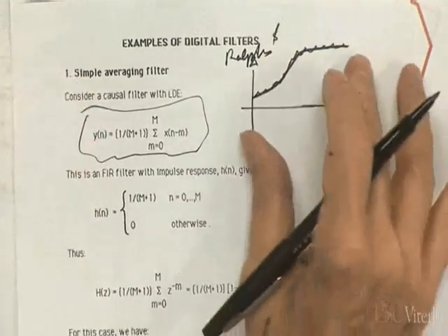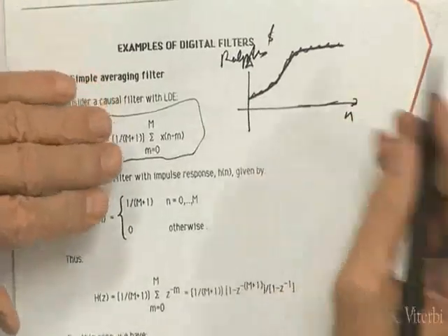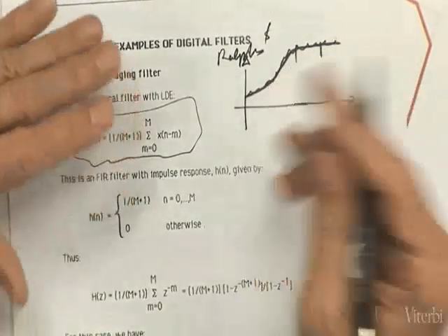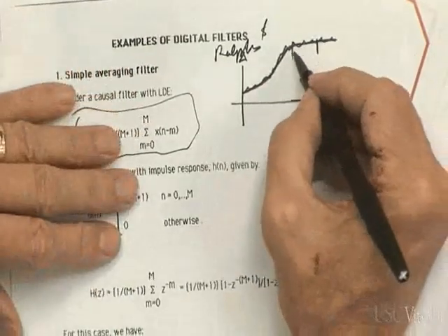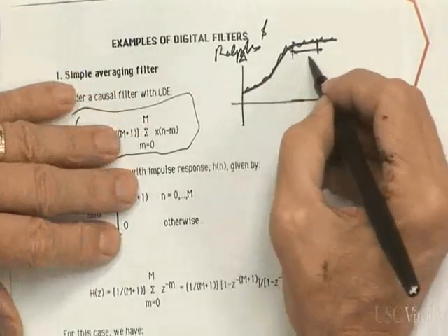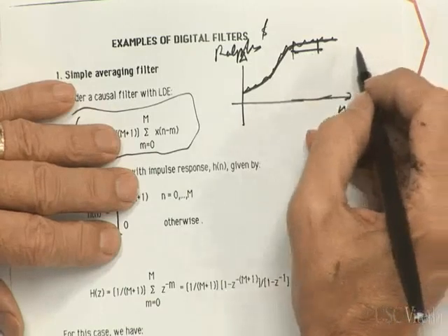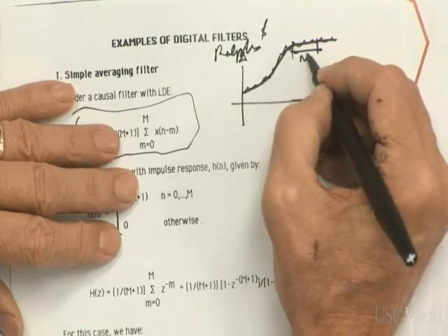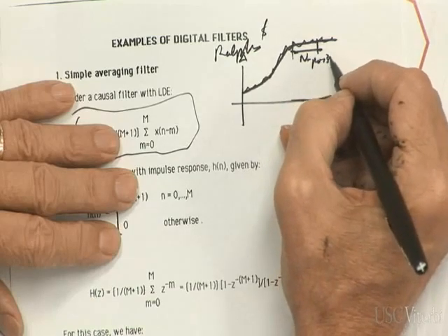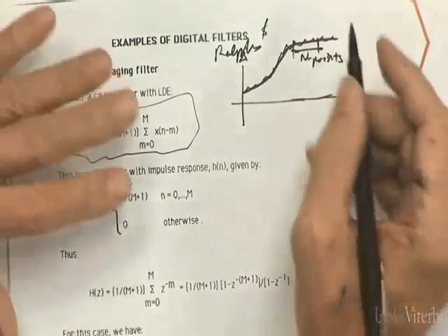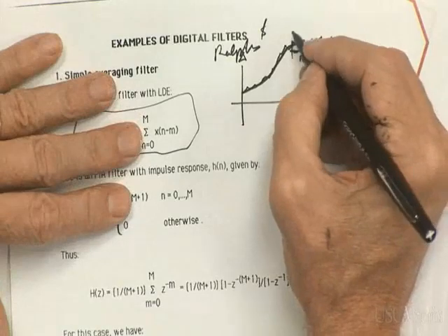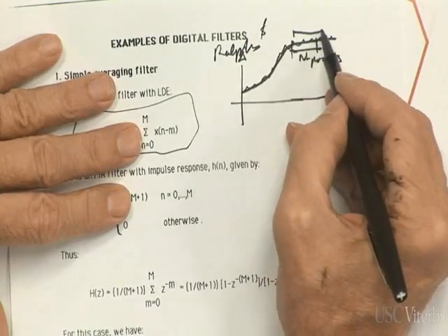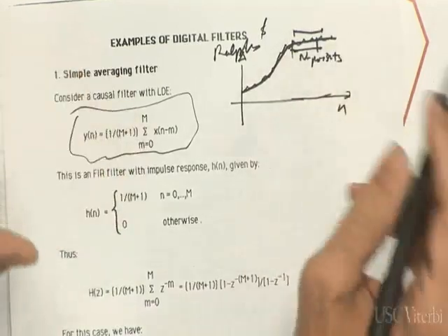Well, what you could do is you could use a running average. By running average, you would take this many points, whatever that length is, it's up to you, and compute an average out of that. So average these points. And then slide this window, n points, slide it by n points, nope, slide it by 1 point. And you get this window. So you're getting highly overlapped windows, and you compute the average over that.